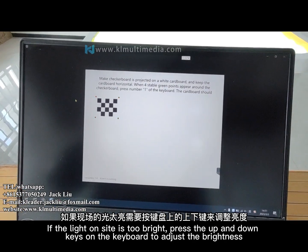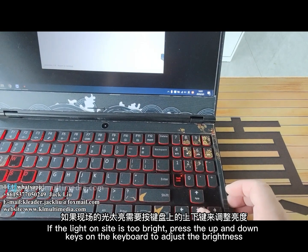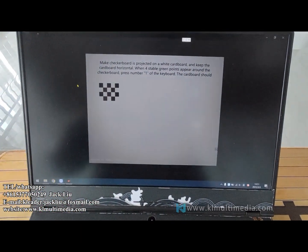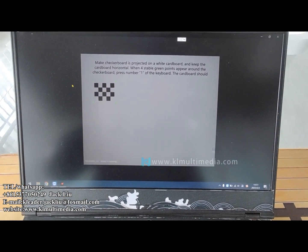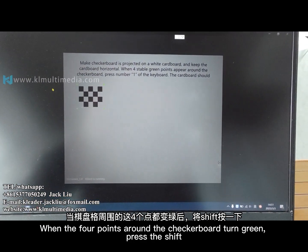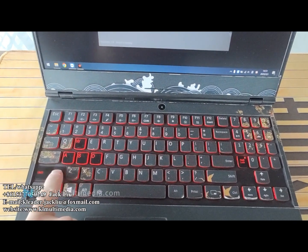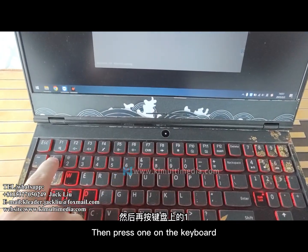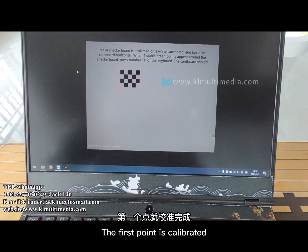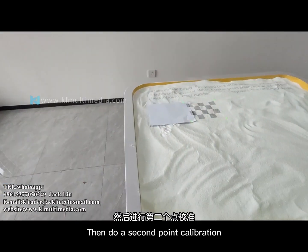If the light on site is too bright, press the up and down keys on the keyboard to adjust the brightness. When the 4 points around the checkerboard turn green, press the Shift. Then press 1 on the keyboard. The first point is calibrated. Then do a second point calibration.